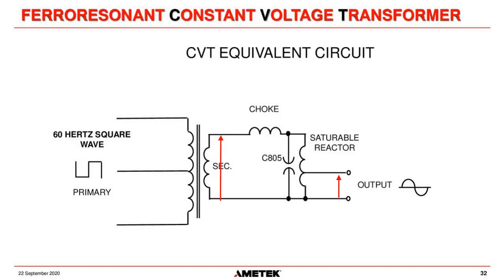And the reason we do it like this is that when we operate on batteries, as the primary voltage decreases, the secondary voltage stays the same. So it's kind of a brute force method here. You just run that transformer right into magnetic saturation, and our voltage is fixed then. It doesn't budge. And that goes from no load to whatever full load is, and actually beyond, because these things will operate generally up to about 125% of their rating.